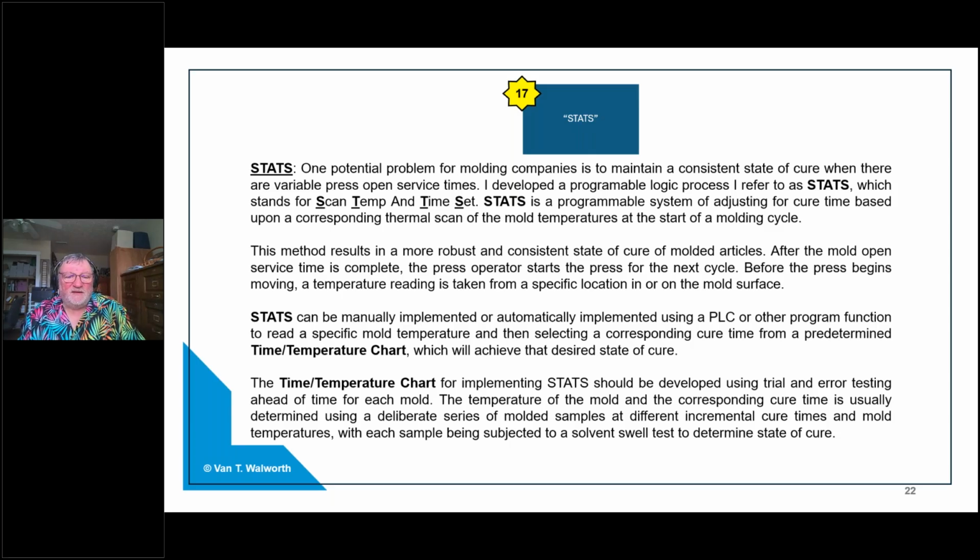And so if in advance of that process cycle, I've done some process engineering and perhaps used a solvent swell test and other methods, I want a certain state of cure for my part. It's imperative that I have a certain state of cure for my part, or it won't actually provide the function and requirements that the customer needs. And so I know that if I have a certain temperature and a certain time, it gives me the state of cure that I need for a functioning acceptable part.